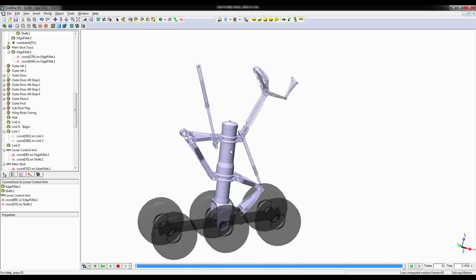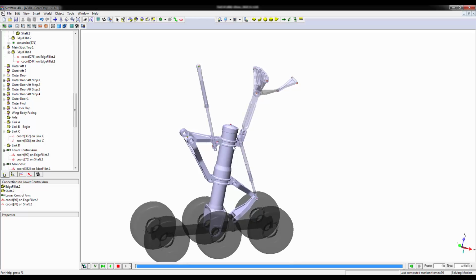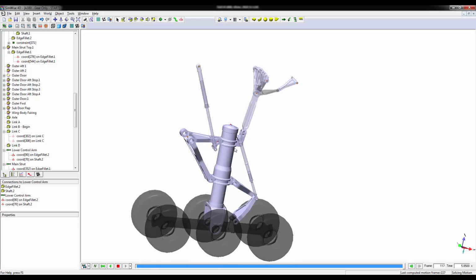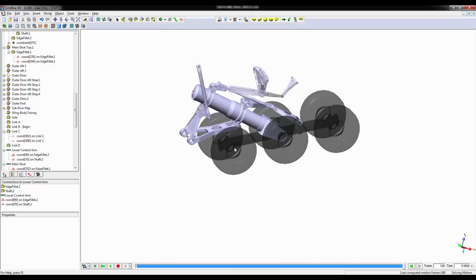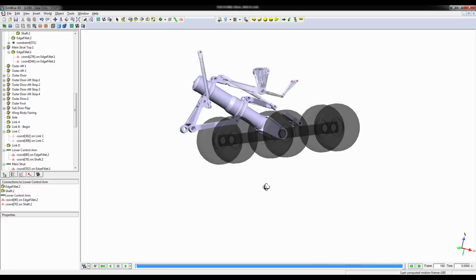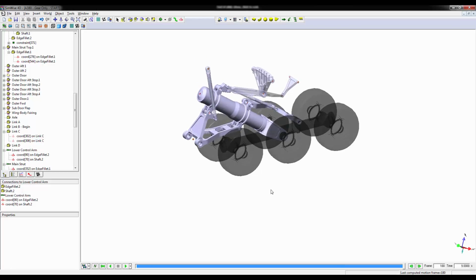So we can create meters for just about anything in here. Chord positions, constraint forces, accelerations. And we create the meters in advance of running the simulation. The reason we create them in advance is it helps the simulation run more efficiently. It's not necessarily calculating all the information and outputting it when you don't necessarily need it.